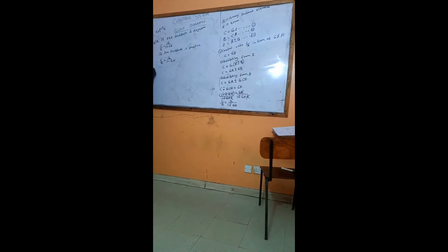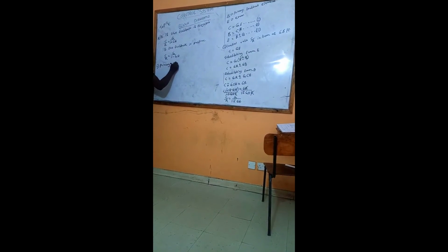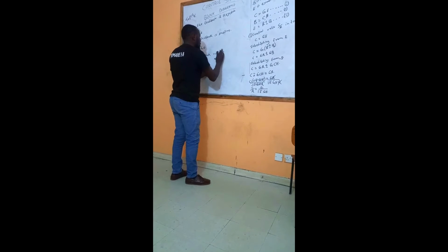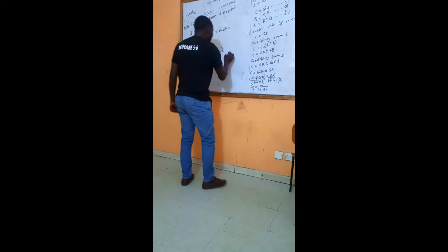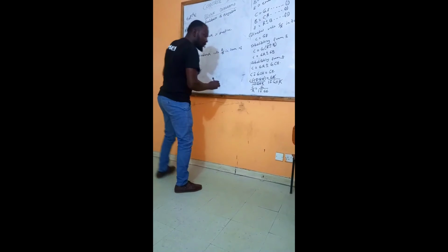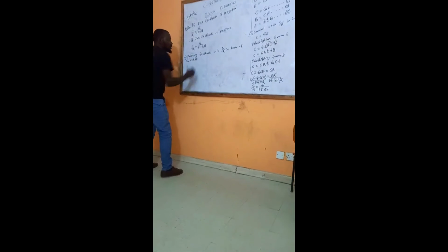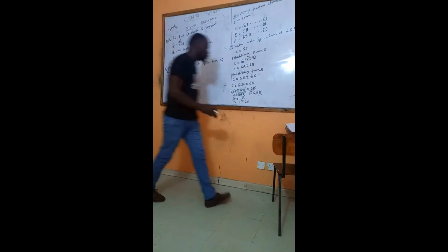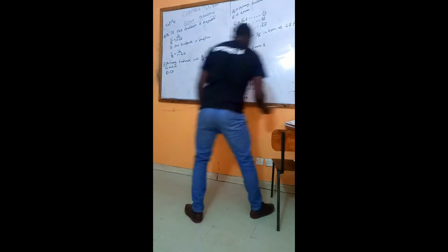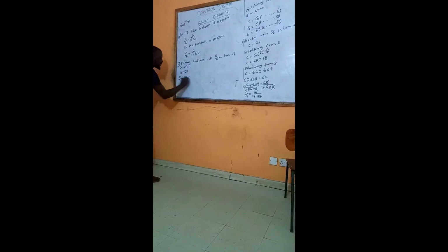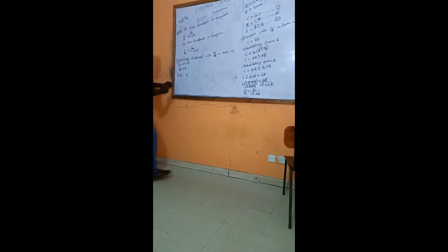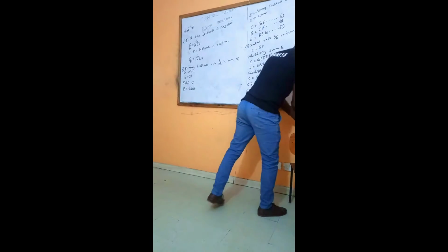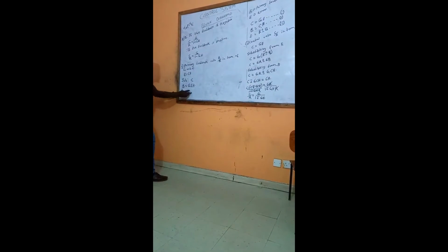Roman 2, right? The primary feedback ratio, that is B over R in terms of G and H. So you need to write for me first of all the formula, B is equal to CH. Now you substitute the C. We have the value of C here. Now we'll have B is equal to C, C is GE multiplied by H. And then the second thing you need to do, you substitute E.